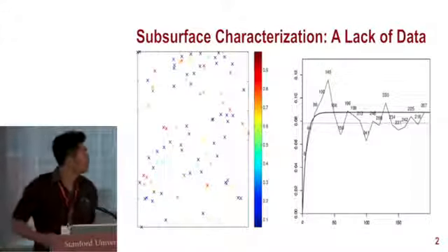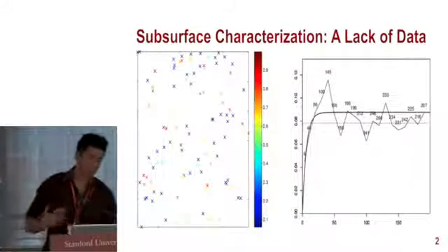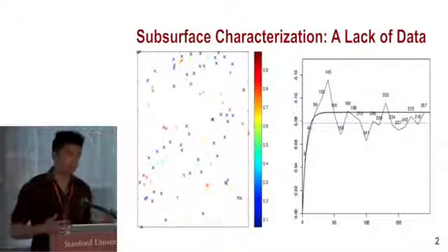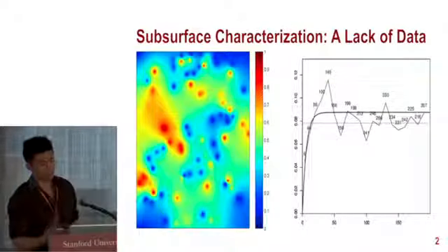So geostatistics was developed for this purpose. Geostatistics was developed in the 60s with random function theory. It requires modeling those covariances that Jeff described, and this is usually done using a variogram. The problem with the variogram is that it is somewhat difficult to model, but it also requires a mathematical decomposition of the data. This decomposition is difficult because it essentially boils down to you have two unknowns and one equation. In this particular example, we took 100 data points and we sampled, and we used these samples to generate this estimate of a region.